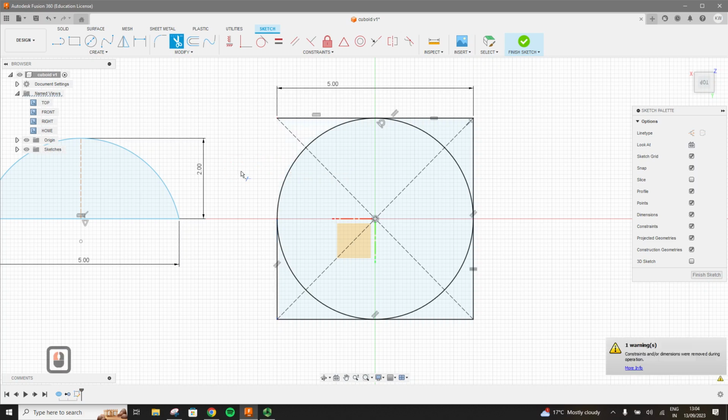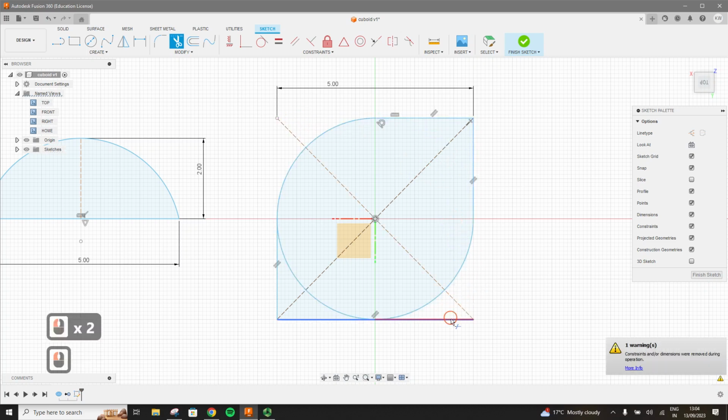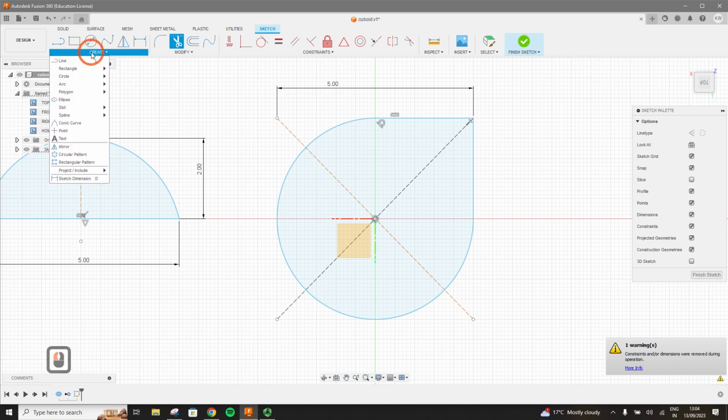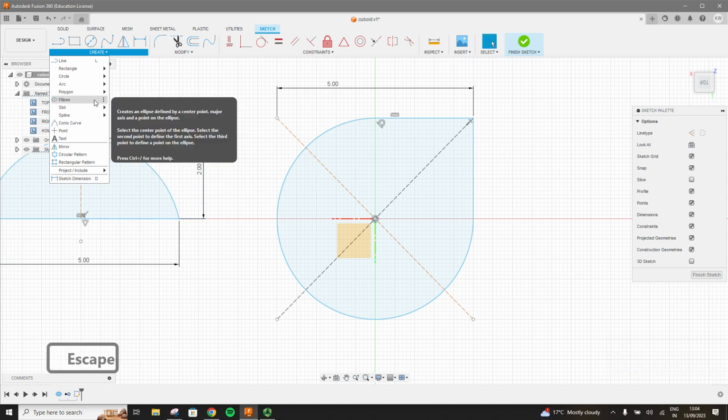If you click on that, you can see that just disappeared. In the same way you can remove this part, and this part of the circle. We can also remove the construction edges, but it doesn't really affect anything. Okay, so that's some of the commands that we have covered. We are still in the trim command, so let's press escape and get out of it.